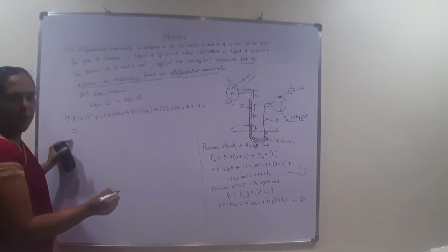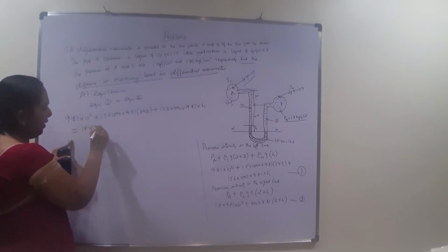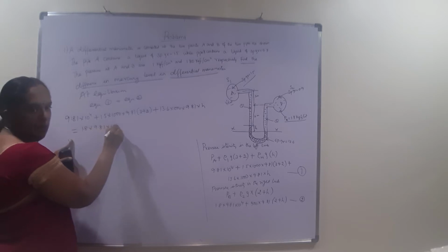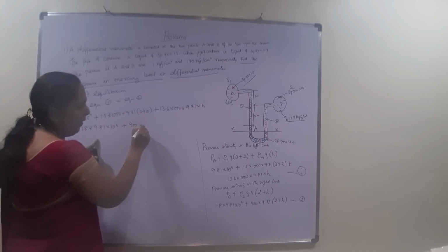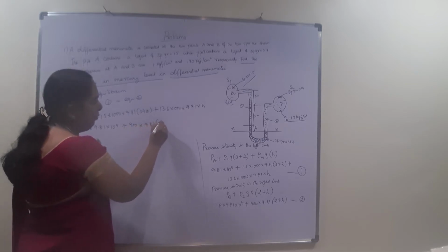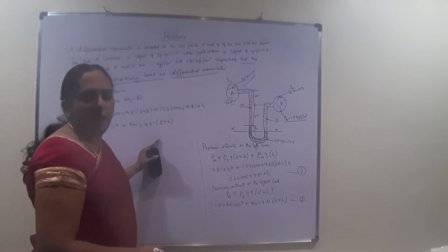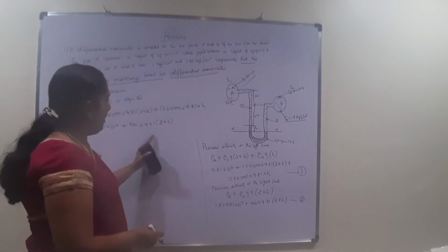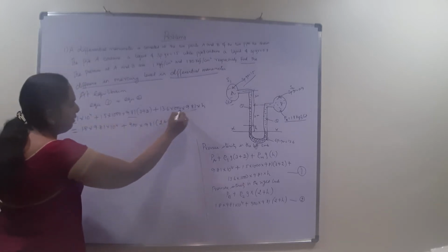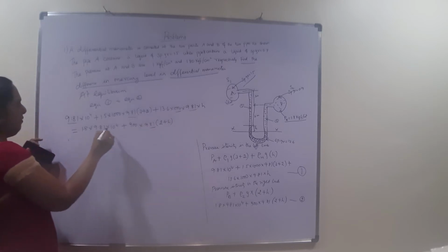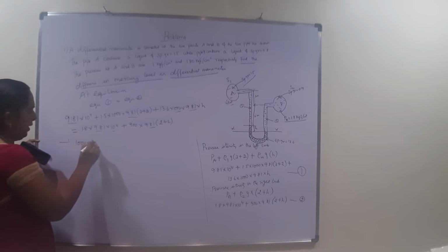That is equal to the equation in the right limb. So what is the equation in the case of the right limb? It is 1.8 into 9.81 into 10 to the power of 4, plus 900 into 9.81 into 2 plus h. Am I right? So this is the equation we are getting in the right limb. When we equate these two, we could observe that 9.81 is in every term and 1000 is also there in almost every term. So we are dividing entirely by 1000 into 9.81.